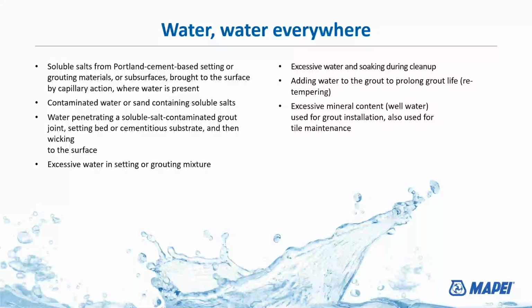It just can't be untreated well water, especially if you've got water that smells like rotten eggs. You've got a lot of iron in it, and that's caused a lot of iron sulfate, and it's causing it to have that rotten egg smell. That water would definitely not be good. We've all heard the stories of people using bottled water in grout. Yes, absolutely, that is okay. But again, too much of it is going to cause a problem.